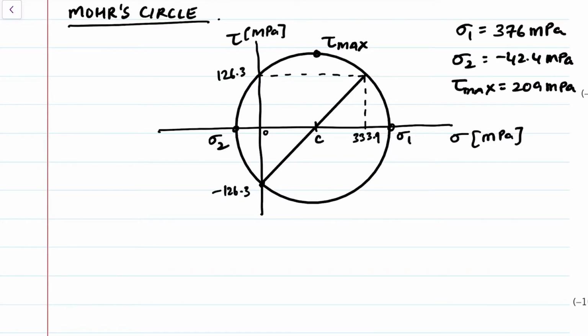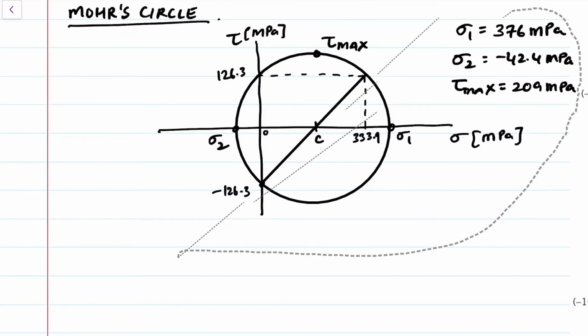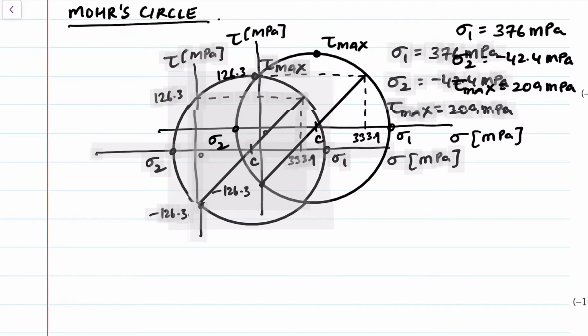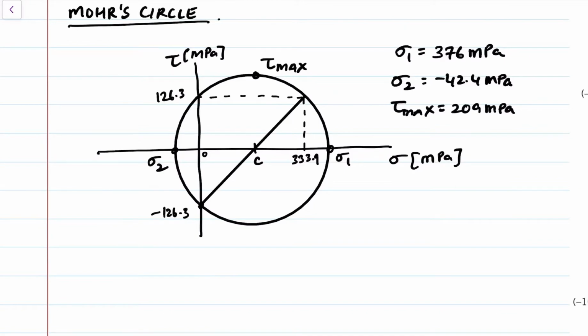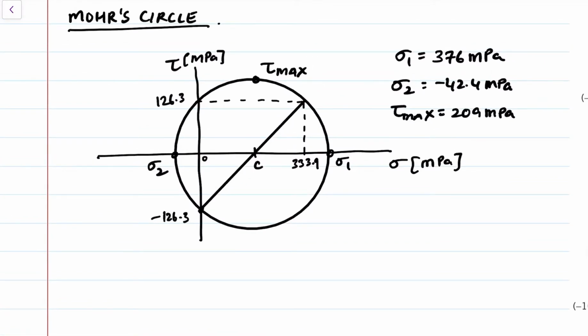Okay, this is the center. All right, so these are the values you got. Well done. You have perfected all you need to know about Mohr circle for this class. Again, I only drew a 2D Mohr circle simply because the original circle crosses the shear axis, so I don't need to worry about a possibly larger circle. But if you want, you can draw in the smaller circles in the middle, and it'll be totally fine.